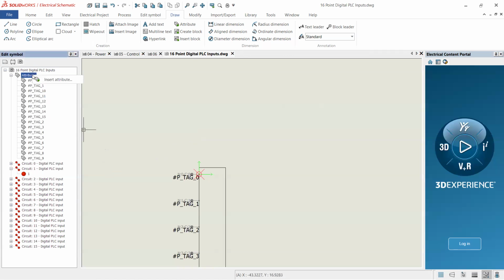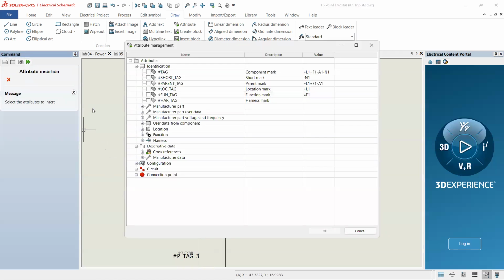But we can right click on attributes and insert, and we'll get a list of all kinds of stuff we have. The CB502 thing, that's a tag, right? That's what we want. We need the tag. That'll be, for instance, PLCIO1, whatever we name it when we get it in, that's it. We need the tag.